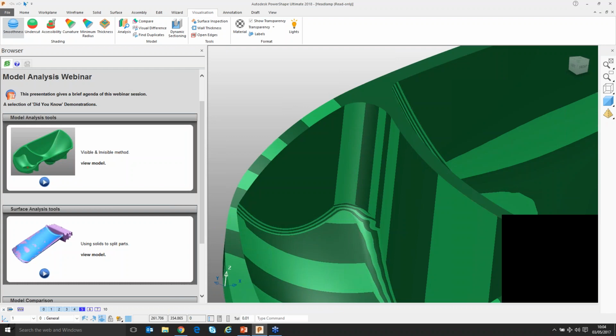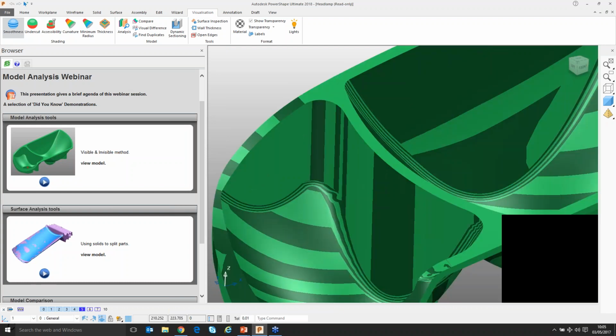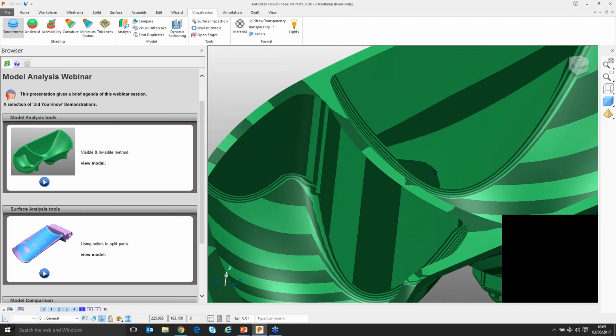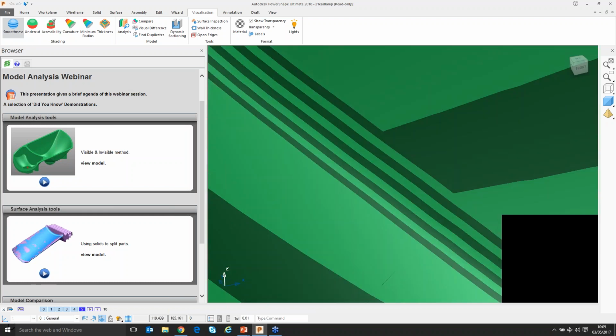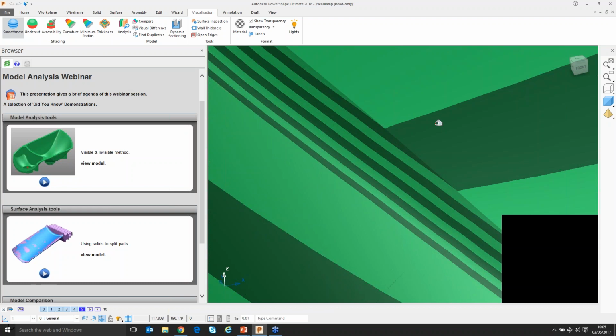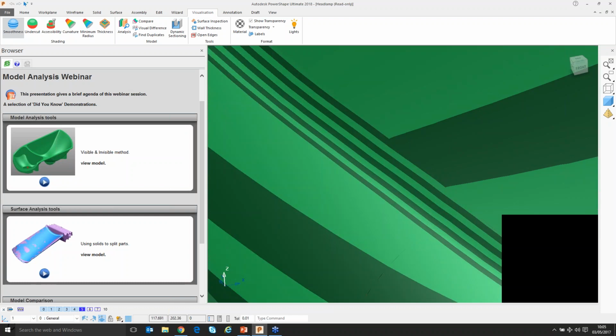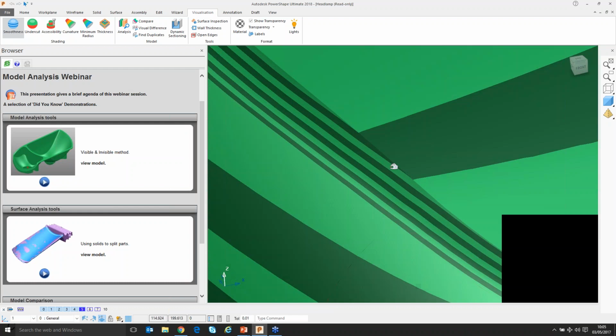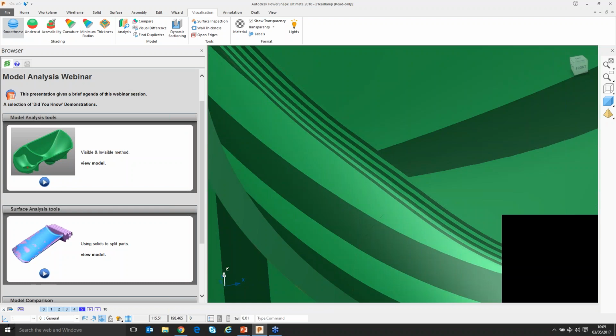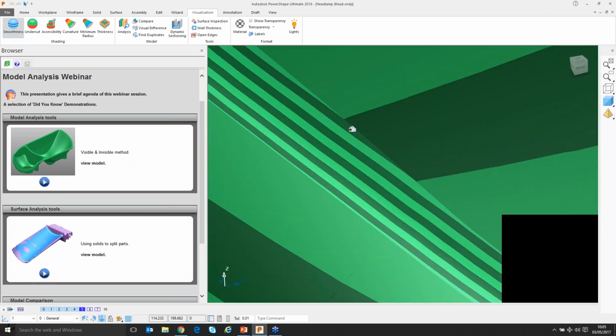So what about C1? What does that look like, where we have tangential continuity? Well, if I were to wander around somewhere on this model, let's pick this fillet here, for example. Can we see here that we have a dark stripe which matches into a dark stripe on the opposite surface? Now, it's a very different direction, but they match, they are in phase, and that tells me that these two surfaces are not only positionally the same, but they also share the same tangency. There's C1 continuity here, they're tangent along this edge. The fact that the shape of this is so different tells me that that's all they are, though. There's no matching radius, if you like, no matching magnitude in this area.